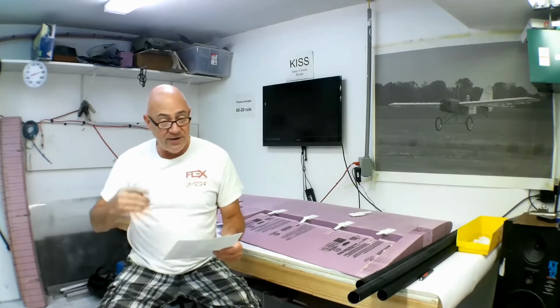Material used in the spar. In many built-up spars I use spruce as the top and bottom spar. I use balsa wood as a shear webbing, and I'll use either light plywood or balsa as the ribs. Once you put that shear webbing on, and if you epoxy it right, and you really know how to put shear webbing on, you end up with a truss design like you see in a bridge. And that is one of the strongest and lightest spars you can build.